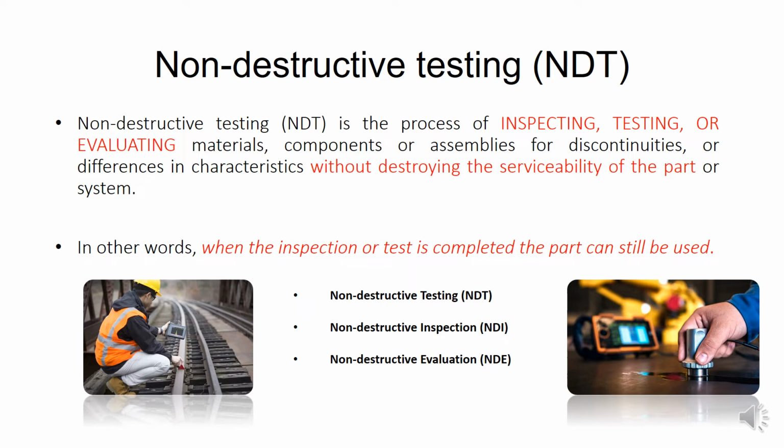So if we have to define non-destructive testing, then it can be defined as a process of inspecting, testing, or evaluating either materials, components, or assemblies for any discontinuities. These discontinuities can be a flaw or a crack, and during inspection, it should not destroy the serviceability of the part. So, in simple terms, it is the process of testing